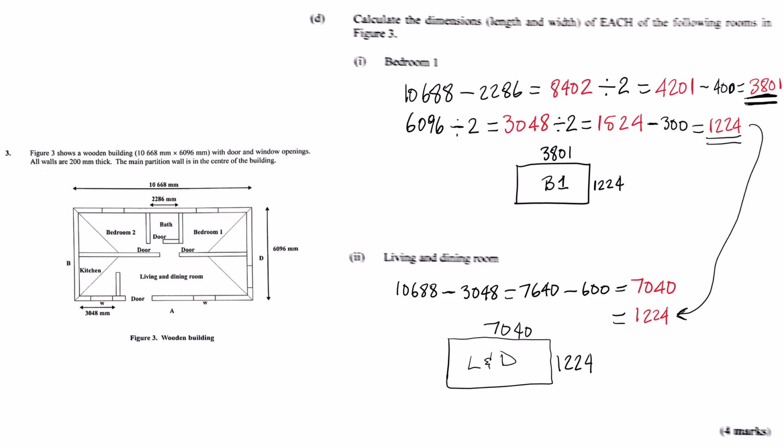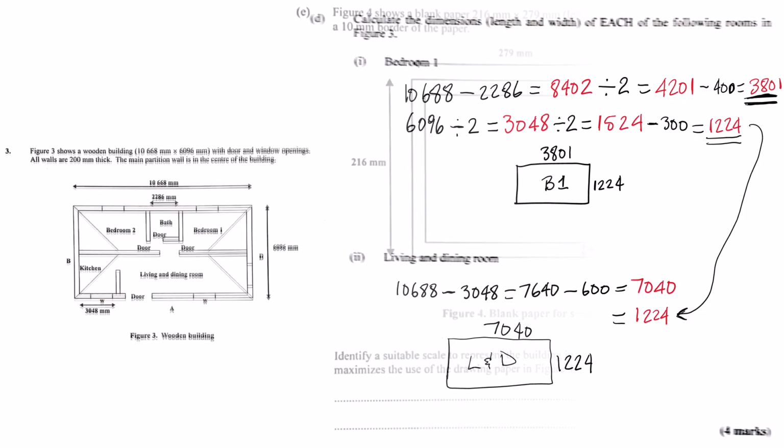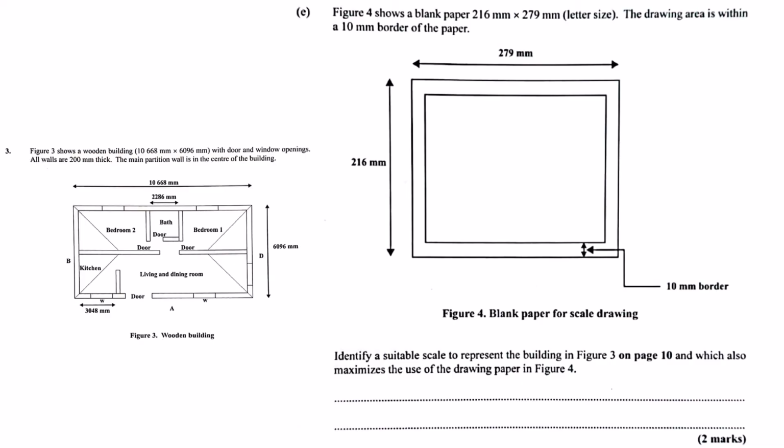And finally, this idea of drawing scale. Why is that so important, and how do architects decide which scale to use? Drawing scale is absolutely fundamental because we're trying to represent something real, often something huge like a building, on a much smaller piece of paper. Right. The scale tells you the ratio between the size on the drawing and the real size. For instance, a common scale is 1:50. That means 1 unit on the drawing, say, 1 millimeter, represents 50 millimeters in the real world. So everything's shrunk down by 50 times. Exactly. Everything is shrunk proportionally. If you ignored the scale, well, you might order materials based on the drawing measurements, and they'd be ridiculously small.